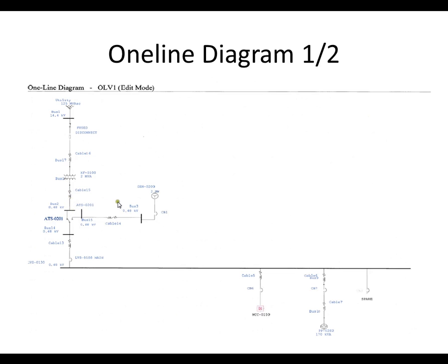If the utility power fails, you've got a generator right here, and that feeds into an automatic transfer switch that will switch between whichever supply is actually supplying power at the time. From there you'll come down into the low voltage switchboard. This is the main breaker right here, and from here you've got a bus work that distributes the power to the motor control center, this 480 volt power panel, and there's actually another one that should be duplicated here.